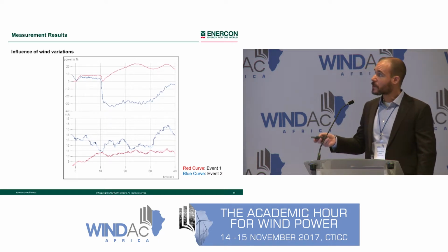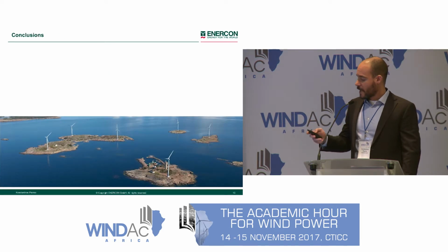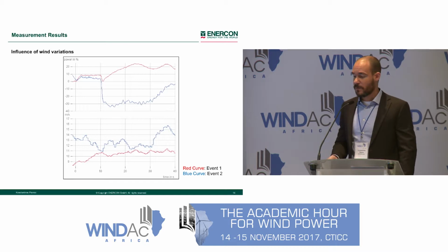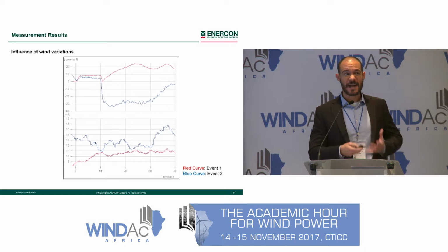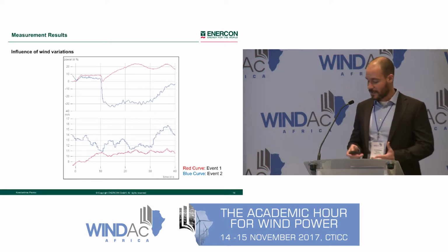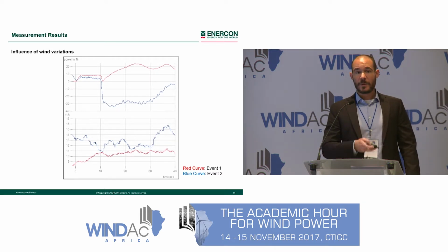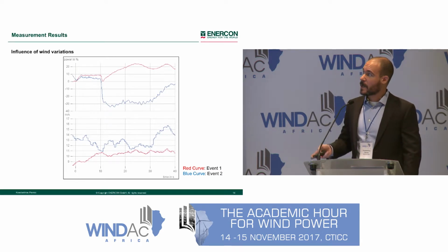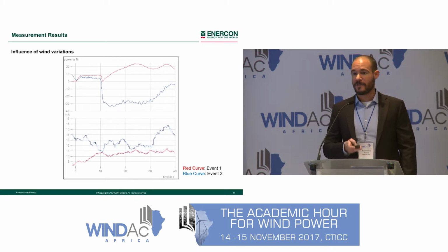Here the same color is used for the active power output and the wind speed of each event, and two triggered events using exactly the same parameters can result in a totally different performance during the recovery period, exactly because of the rapid change of the wind speed during the recovery period, and despite the fact that, as you can see, both recovery periods started at almost the same active power output.